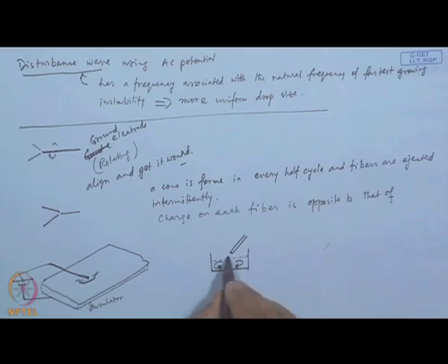So, in the atmosphere, if you go beyond the threshold ionization voltage, that means this atmosphere is getting ionized. In that case, the co-ions are repelled from the tip. So, if this is positively charged, then the positively charged ions would be repelled from the tip and they will collide with electroneutral air. Air is otherwise electroneutral and these ions are repelled. So, there will be a corona wind developed due to the momentum transfer.